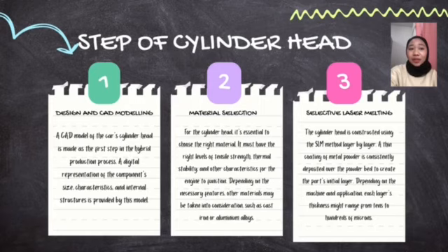The next step is cooling and layer repetition. After each layer is selectively melted, the newly formed solidified metal needs to be cooled to a suitable temperature before proceeding to the next layer. The cooling rate is monitored and controlled to prevent distortion or warping.